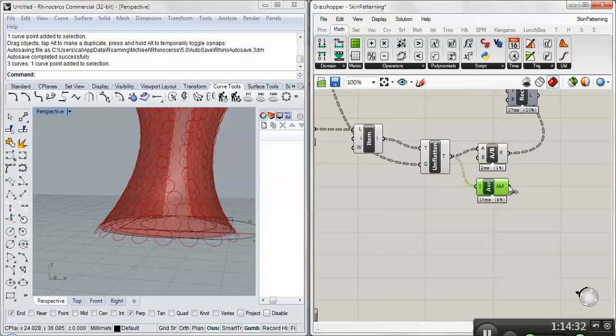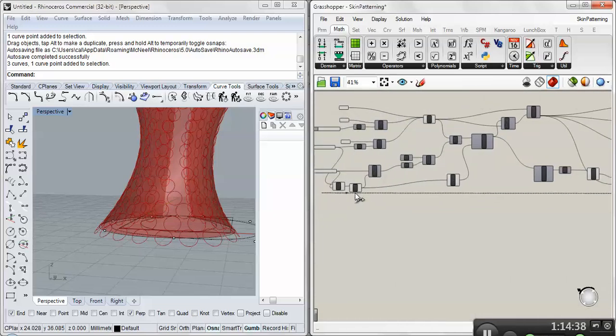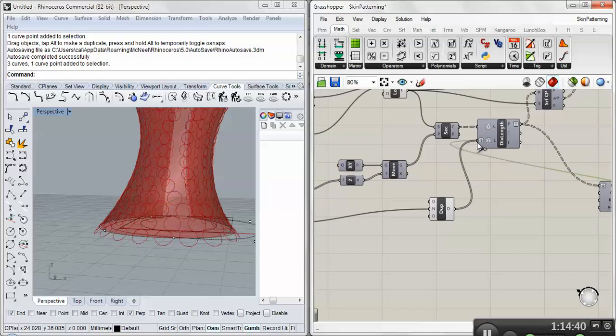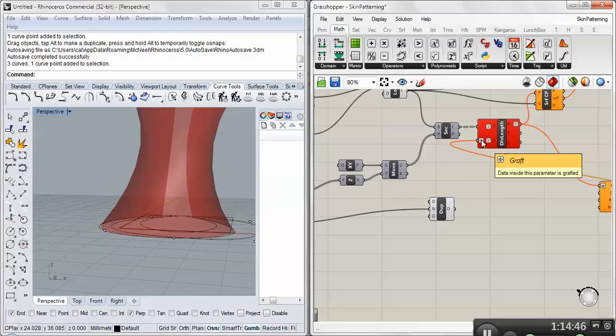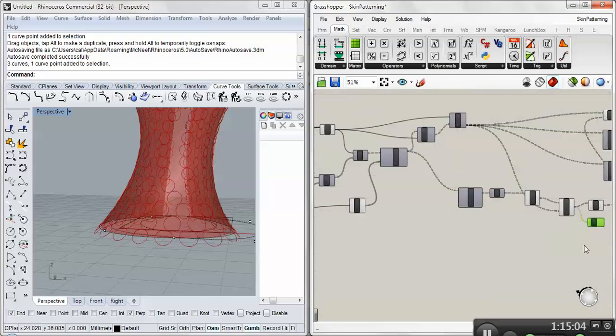And here's where I say, okay, well that's what I want to feed back in over here, but I already am feeding something in there. So I can't just, we can try it, but it's probably wrong data structure anyway. But I already started with something. If I change it again, it will create this loop, and I'm not going to actually be able to get the result I want. Since there was something that already created this average, if I feed back in the average will be recalculated, and you can't do something that loops back onto itself within normal Grasshopper. That's what the hoop snake will let you do.